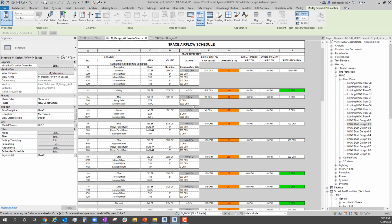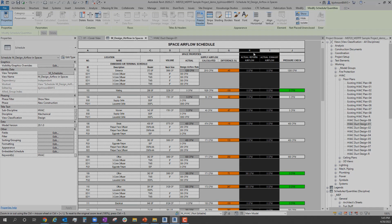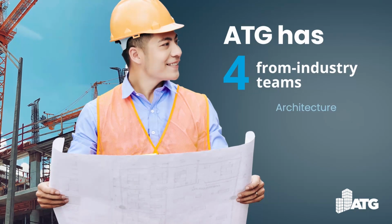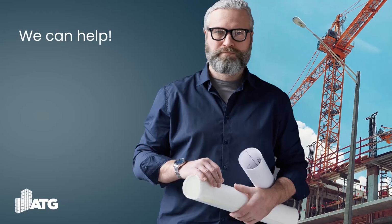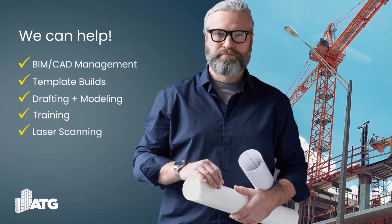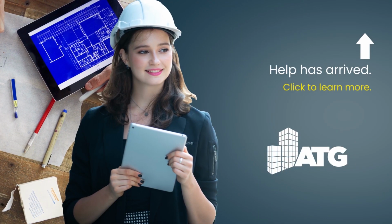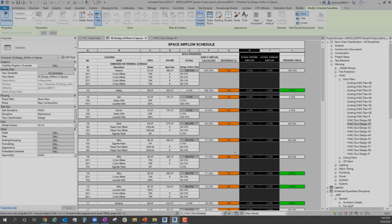What if I had a way of showing only supply terminals, not return and exhaust, number one, so I can remove or hide these extra fields, because I don't really want to see those. I'm just going to do that now. I don't even know if I want pressure check, but I'll leave it in there for now. Well, let's hide those out.